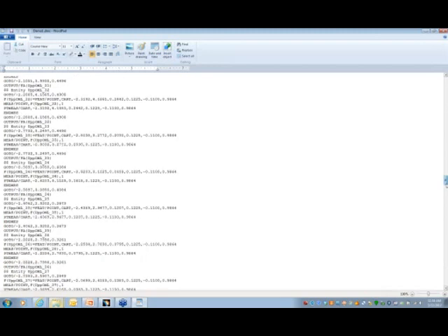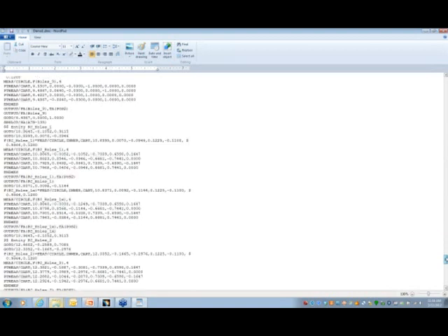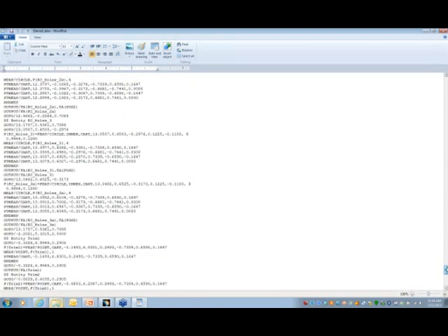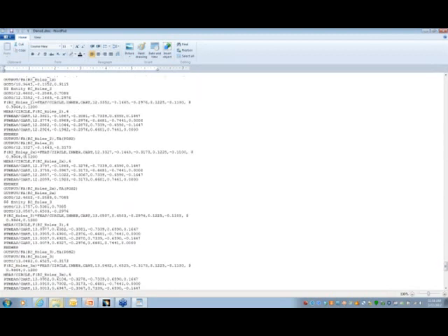Later on, as we measure the holes, here's where the holes are. These are the PT measure hits in holes. And then when we did the holes at 2 depth, what we ended up getting is we had 2. So this was the top hit, and this is the bottom hit. And we could even construct a line from the bottom and the top if you want to see what the vector is. But we're probing the top of the hole and the bottom of the hole. So this is our DMIS.